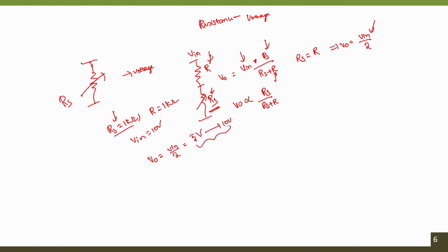What is the total range that you have? A total of 5 volts. But what is the span of the ADC? Suppose the ADC range is 5 volts and the ADC is operated at 5 volts, the total span of your ADC input is 5 volts. Of course, the change that you observe is also 5 volts, and the ADC range is also 5 volts. It may match, but due to the initial offset from the base resistance and the resistance chosen by the sensor, you cannot directly interface into this.